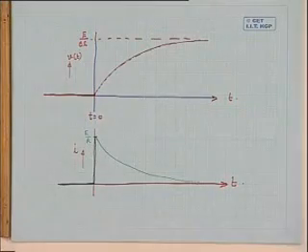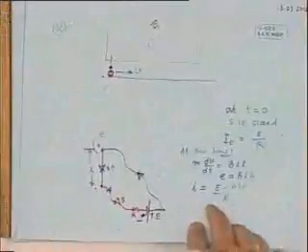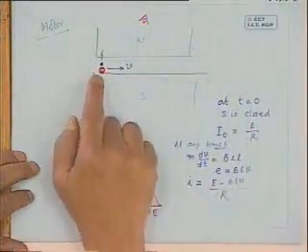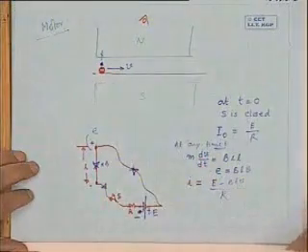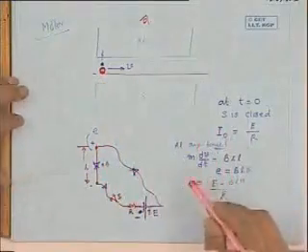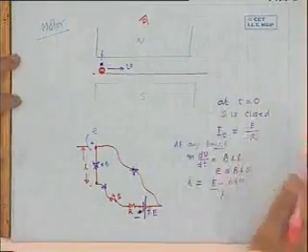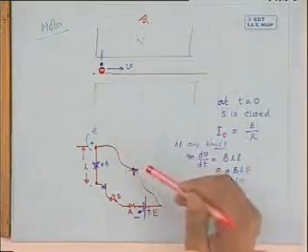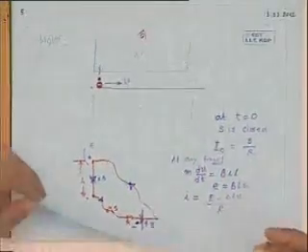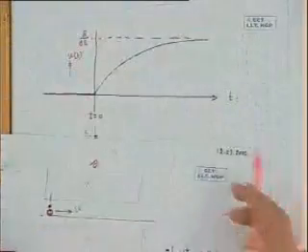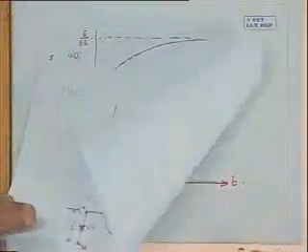The time constant is mR by B square L square. But the important thing we get here is this: if you switch on, initially it was stationary, velocity was 0. You close the switch, then you will find the conductor will start accelerating. Velocity will go on rising. And finally, after some time, depending upon the time constant of the circuit, the conductor will start moving with a constant velocity of magnitude E by BL.